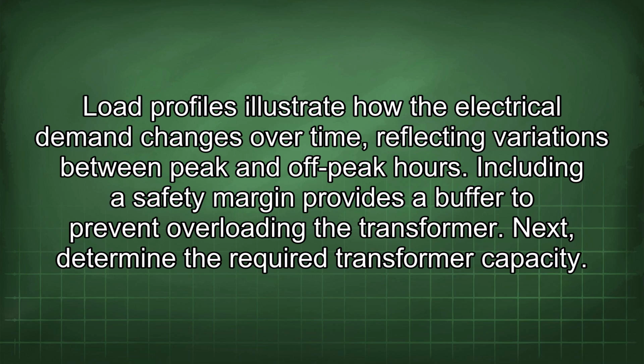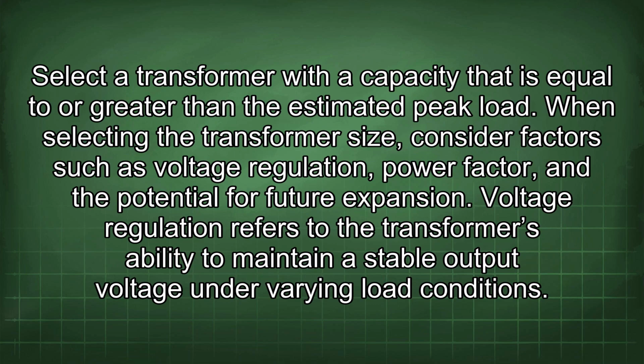Next, determine the required transformer capacity. Select a transformer with a capacity that is equal to or greater than the estimated peak load. When selecting the transformer size, consider factors such as voltage regulation, power factor, and the potential for future expansion.